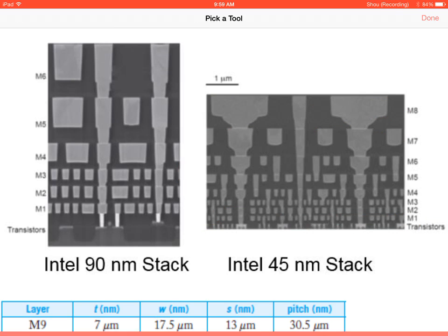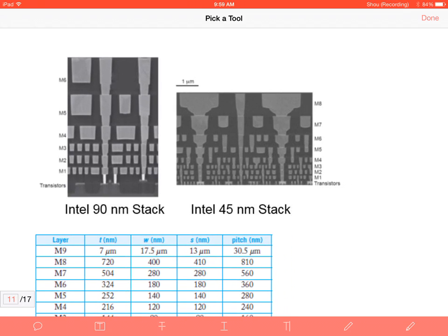Now, if I remember, maybe 2 or 3 lectures ago, I told you that one of the biggest issues that CMOS designers have is they'll design some part of the circuit, and they'll design another part of the circuit, and they wonder why it doesn't meet the power constraint, because there's just this long metal 1 wire. Or they'll use a very thin metal 1 here, and it consumes a lot of power, and they're wondering why. Put them together, have a shorter wire, it'll consume significantly less power.